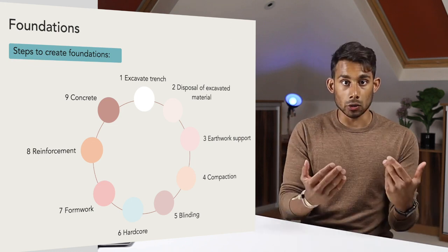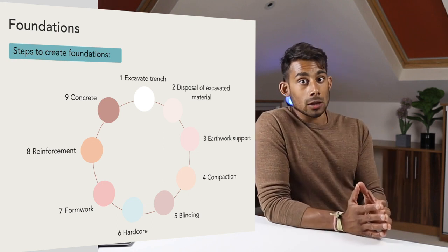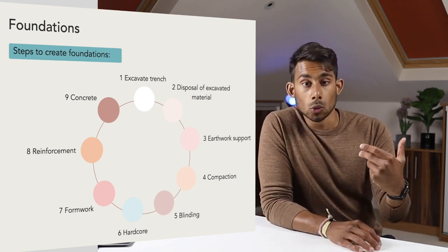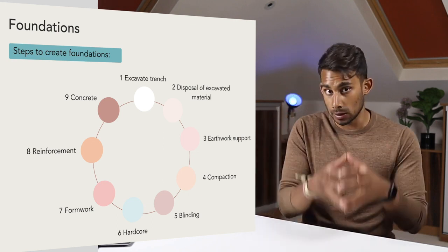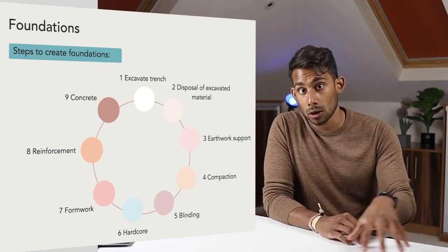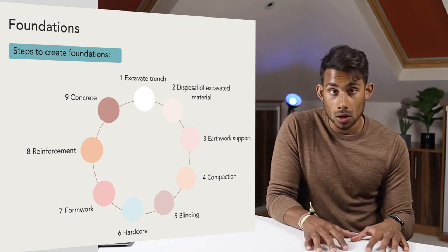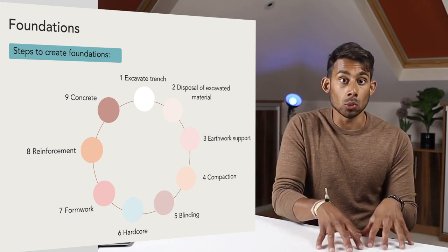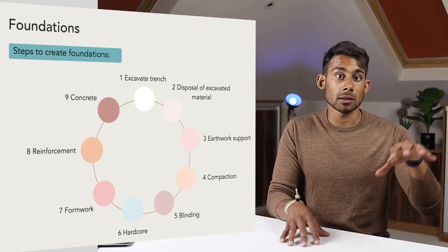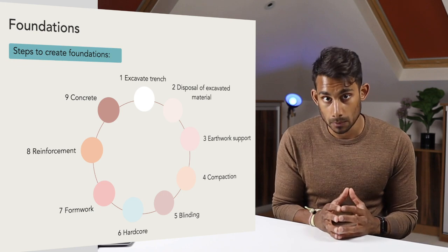Next, we will lay the concrete. Once the site is prepared, the concrete is ready to be laid. As well as the type of foundation, it is also important to know which type of concrete to use. Soils which contain sulfates, for example, can attack concrete over time and cause an expansive reaction. The depth of concrete that will be needed will depend on the use. Footings for small projects, for example, will need to be at least 200 millimeters thick.